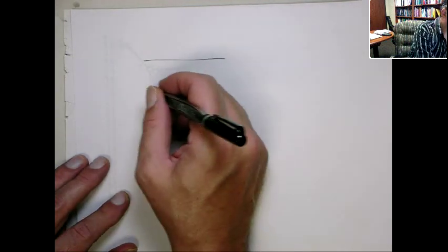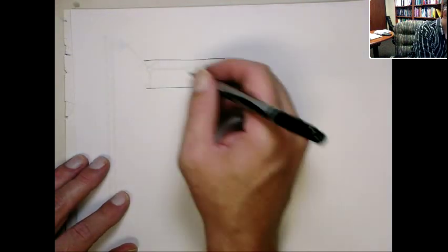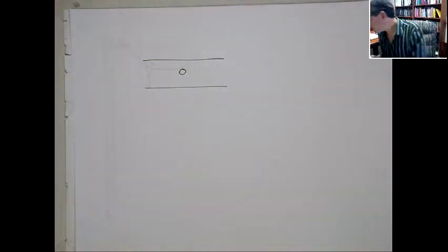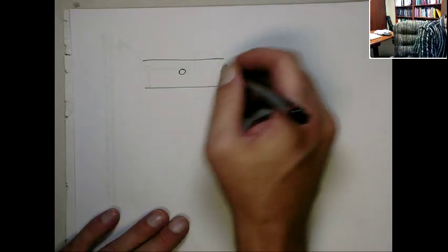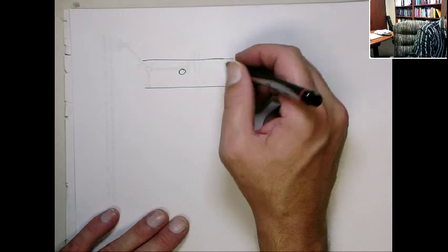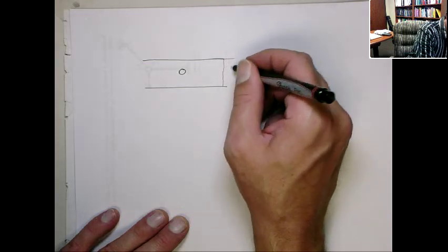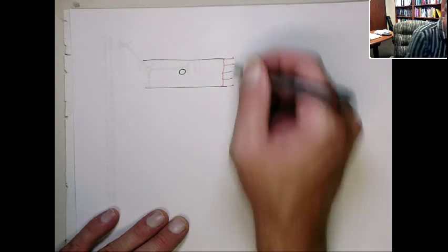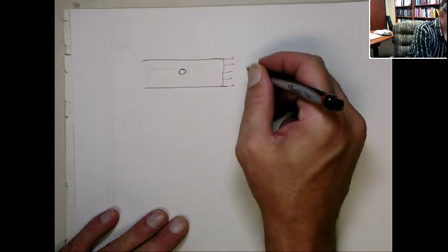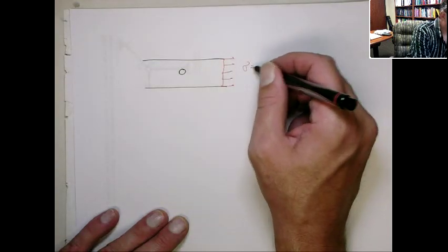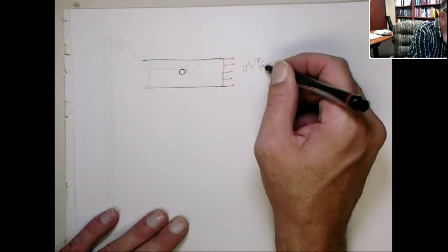a one-dimensional structure, an axial structure, but maybe with a hole in it. And then if you look at that, what you find typically is if you're far away from the hole, but still away from the end condition, so you get this idealized loading situation, right? If you cut here, you see a fairly uniform stress state where the stress is pretty constant over the cross-sectional area. It is the P on A.